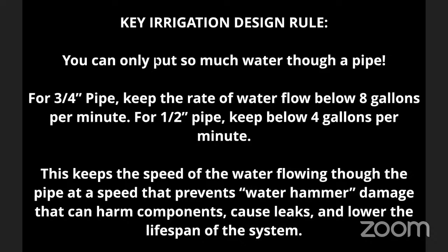Instead of 3 sprinkler heads, if you had 15, that's going to require 5 times as much water flowing through that pipe at any given moment. And so that water needs to travel faster.